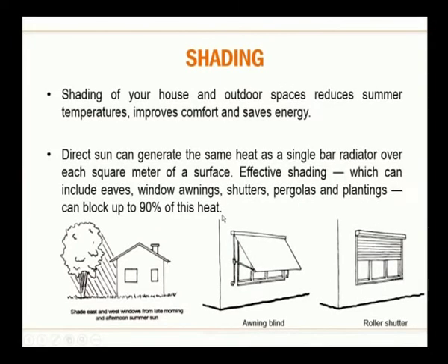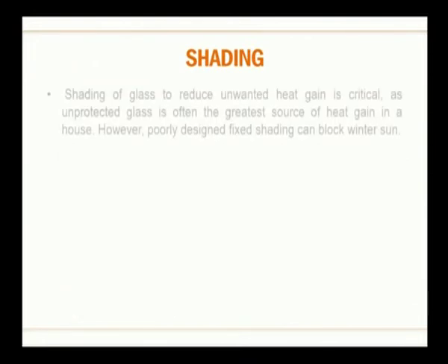So, when you are in a harsher climate with a lot of solar radiation, it's ideal to have huge windows to invite wind, but when you have huge windows, you are also inviting harsh solar radiation. So, for that you must eliminate the direct solar radiation by using different types of shading systems according to your climate, and you can benefit only from the prevailing wind directions according to the specific location.